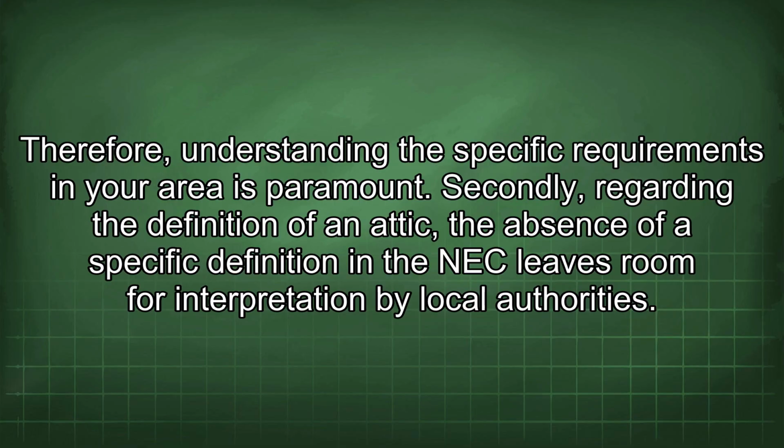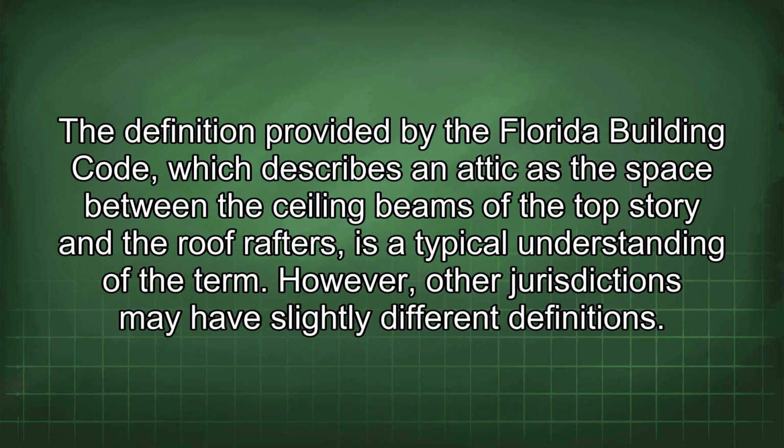Secondly, regarding the definition of an attic, the absence of a specific definition in the NEC leaves room for interpretation by local authorities. The definition provided by the Florida Building Code, which describes an attic as the space between the ceiling beams of the top story and the roof rafters, is a typical understanding of the term. However, other jurisdictions may have slightly different definitions.